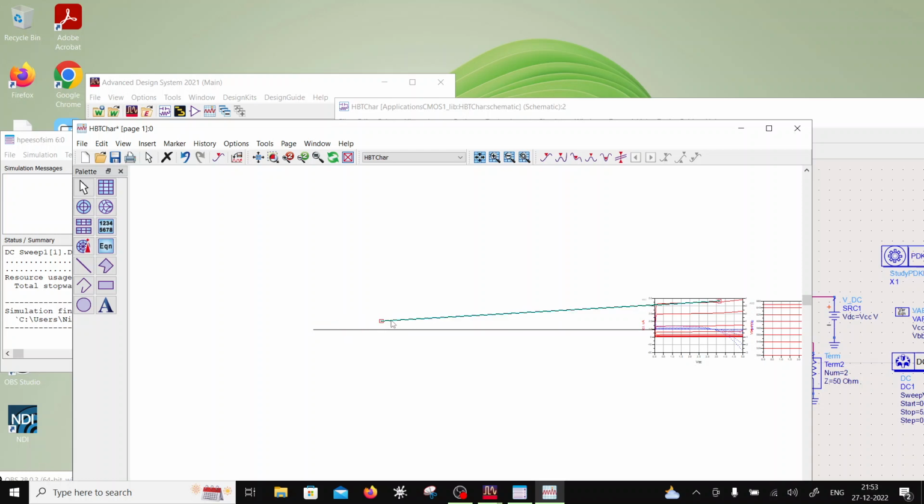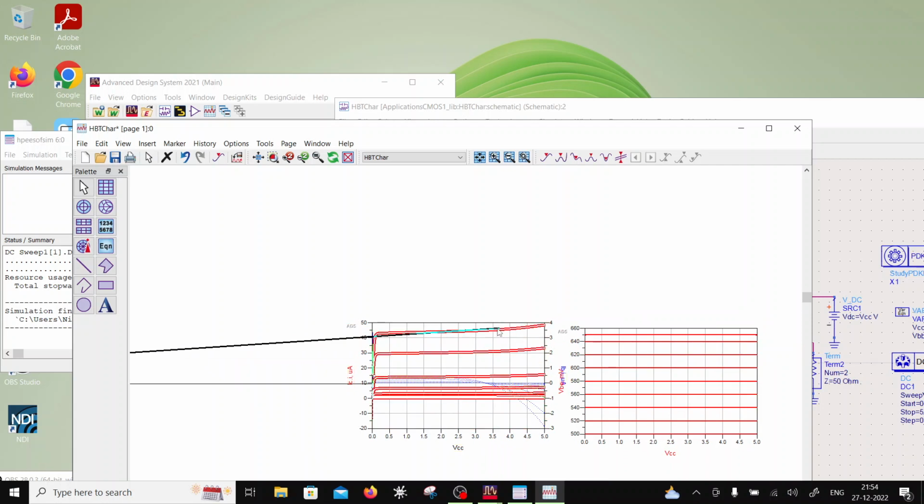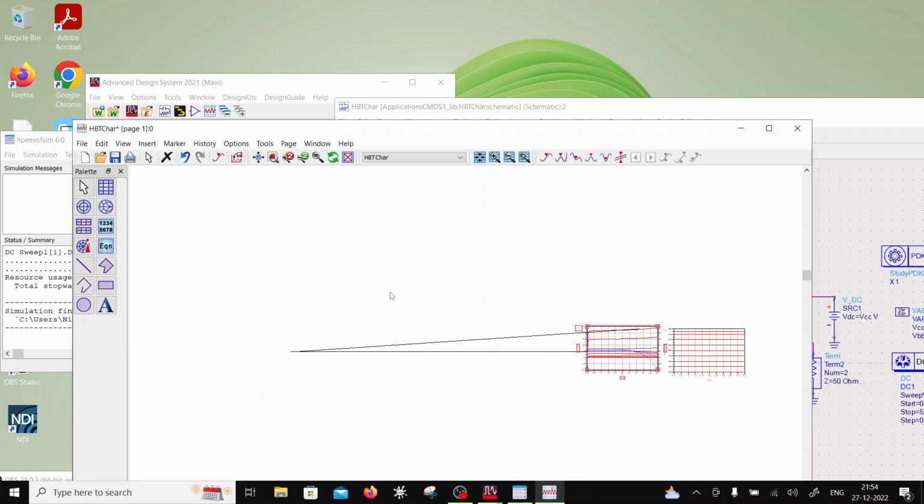So books basically can show an exaggerated value, so the intersection comes in that case very early. Okay, somewhere here. So this voltage is minus VA, or it is called the early voltage, and all the current curves for different IB, different VBE, sorry, they are going to meet at the same point. Okay, somehow I'm not able to grab it, but it's okay. I can draw another line. So basically all are going to intersect at the same early voltage.